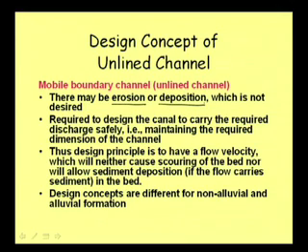Well, when it is an unlined canal, with flow velocity there can always be erosion of the bed and side, and once it is eroded at a particular point, then it is obvious that the canal will be carrying sediment laden water. Once it is eroded, it will be carried by the water. So, from upstream itself it can carry, and within the channel itself it can erode side and bed, and then it can carry the sediment.